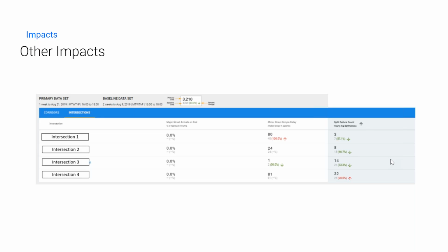The problem was that they just weren't coordinated. That was the thing. One of the intersections, of course, was favored for the minor movements during the PM peak, and with the coordinated plan, there's an increase in the simple delay there, just to ensure that there's a nice queue before it's being serviced, and it's for the greater good of the entire corridor. So it makes sense for this to happen, and there's always a level of judgment that needs to go on top of this as well.